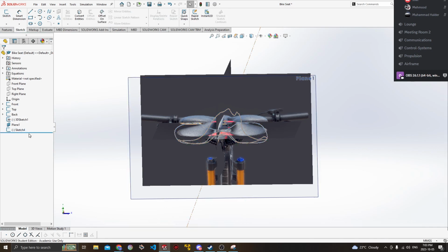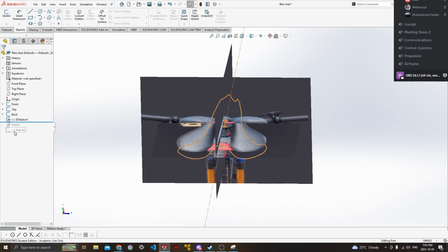What we're going to do is go back. We're actually going to roll this back. So we're going to take this little, I think this is called a rollback bar, if I remember correctly. We're going to roll this back right before we did that sketch. What that's going to do is just remove everything we've done beforehand and keep it in kind of limbo. And so what I'm going to do here is just edit the sketch.